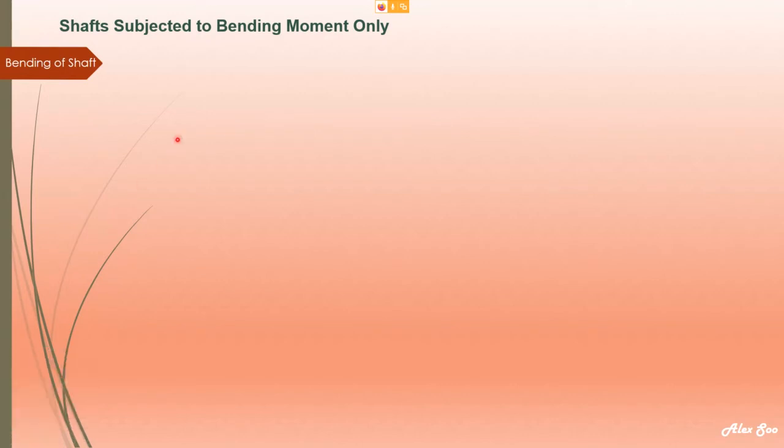Then we have to refer to the simple bending equation. The simple bending equation also will be split into two different sections, based on strength relationship and stiffness relationship. So based on strength relationship, we have M over I equals sigma over Y. What is this M here? M is the maximum bending moment.